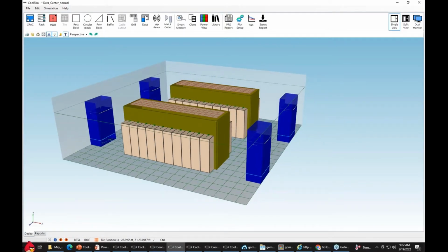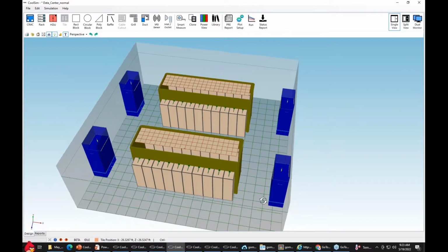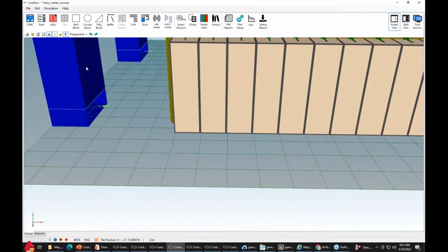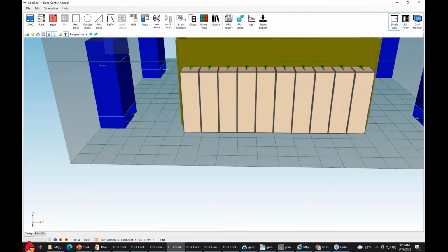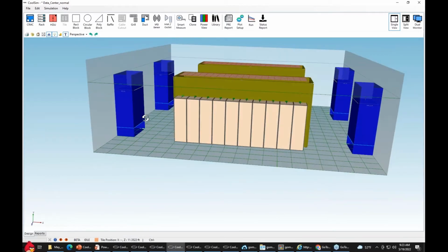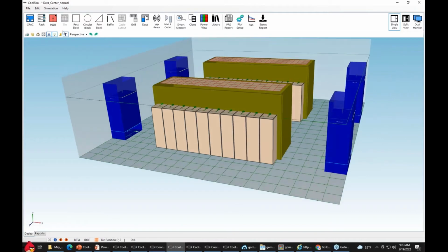This is just a standard data center model. And I've done hot aisle containment here. And I'm supplying cold air down. This is non-raised floor, so I'm coming down through the cooling unit into the room. Okay, the units are tied to the ceiling automatically. CoolSim does that for you. It has a ceiling plenum return. This is a hot aisle design.